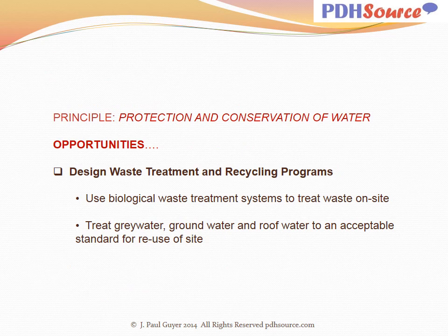Design waste treatment and recycling programs. This kind of crops up in the construction phase, and then in the O&M phase. In the construction phase, simple little things like specifying that the contractor pile the concrete waste over here, the metal waste here, the soil here, and the garbage over here.